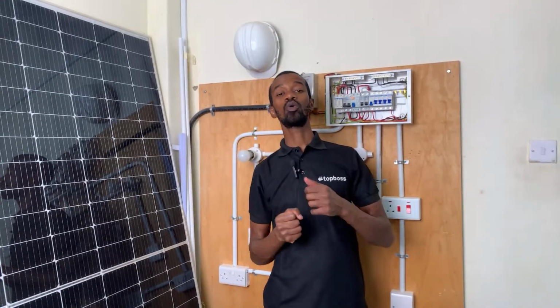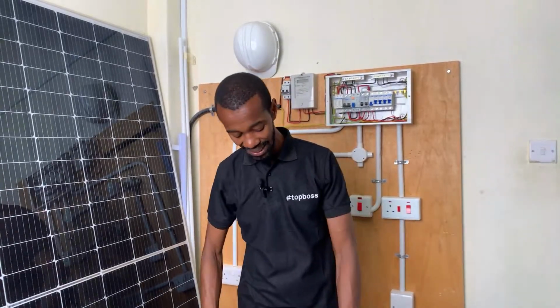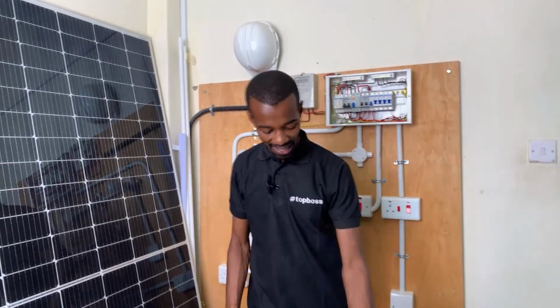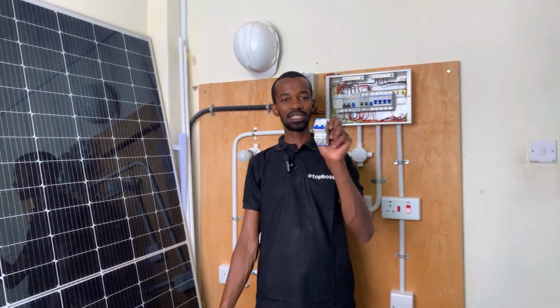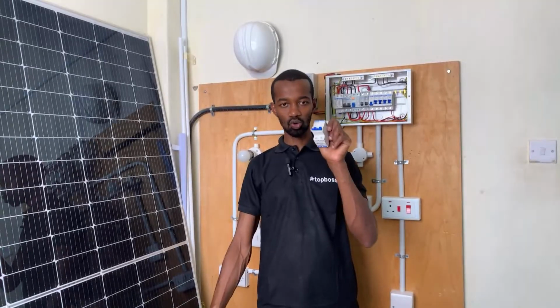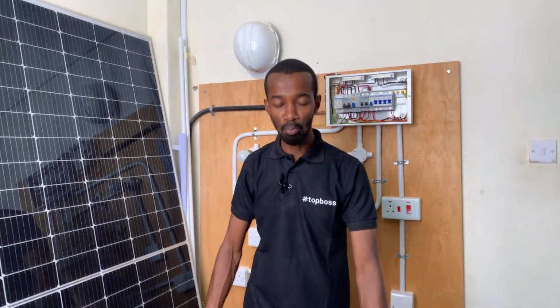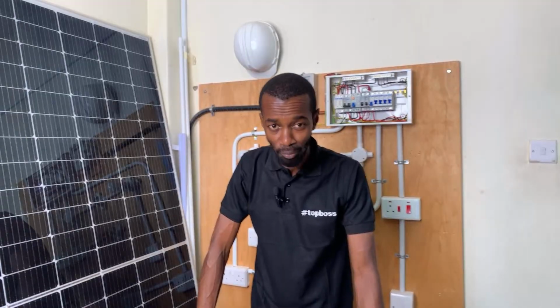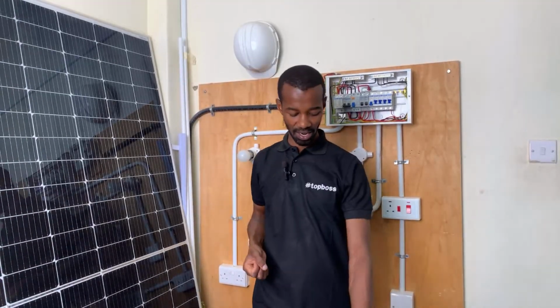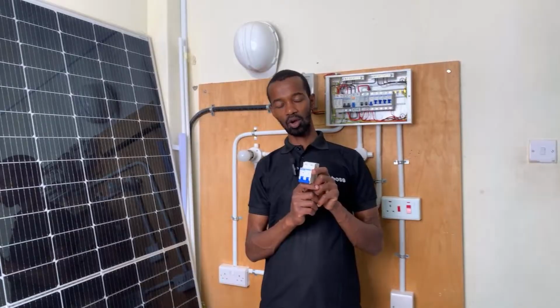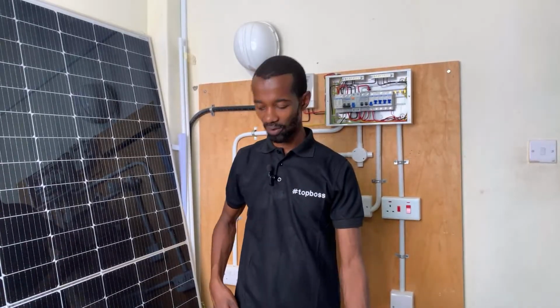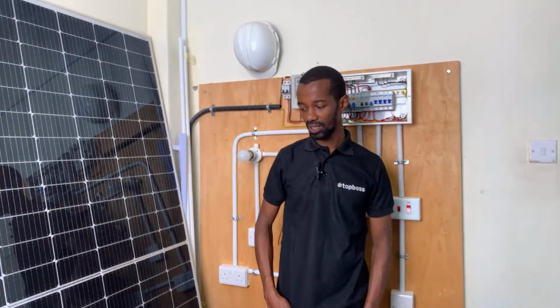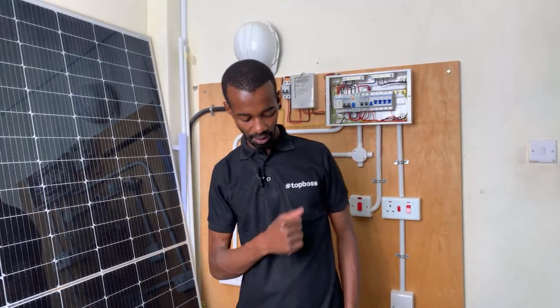An overcurrent is whereby an appliance has been connected to a source of power and draws more current than what should be drawn from that source. For instance, a 63 ampere MCB being connected to a 100 ampere motor, it means that the motor will draw a lot of current from this MCB, causing that situation to be an overcurrent, and that will definitely lead to the tripping of that MCB.